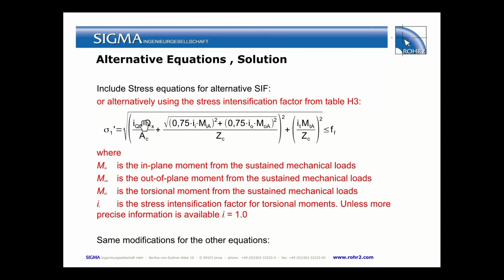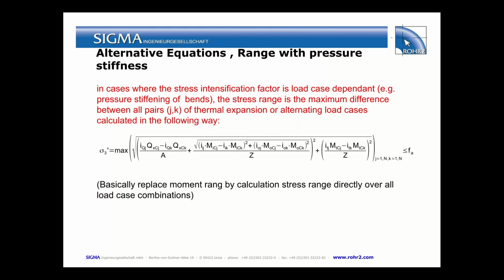And of course this is more complicated than just replacing I by II and IO. Things get even more complicated for the stress range, because now we have to calculate a stress range based on in-plane and out-plane moments, and we also have the fact that the in-plane and out-plane stress intensification factors also are load case dependent because of the pressure stiffening of the bends.